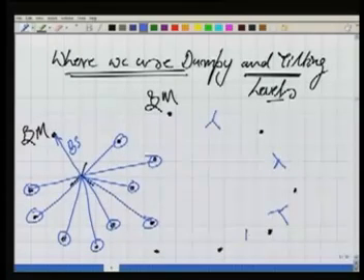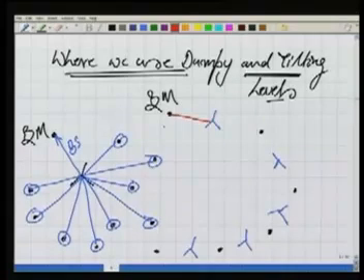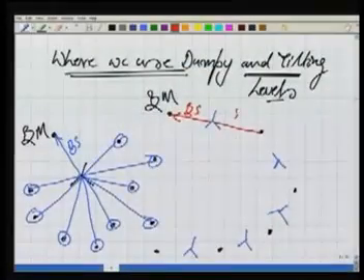These 3 lines indicate the tripod, and first of all I bisect my staff which is kept at the benchmark, and then quickly I level it, because we have seen the procedure of how we level the tilting level. It's a very quick procedure. While I am taking the back sight on this staff, I level it, then I rotate it in the horizontal plane, and again I take a sight which is the foresight.